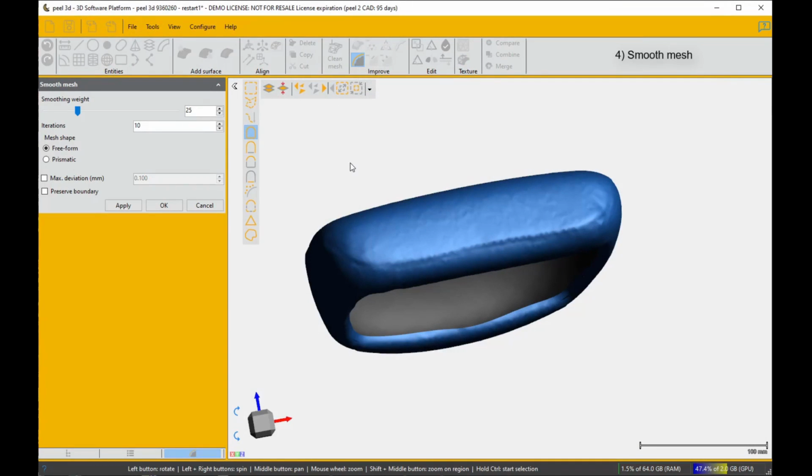Now, I'm actually going to stop the video for just a second and talk about symmetry. This is an object that's symmetrical, and as a pattern maker, you want symmetrical patterns, even if the object, which I just scanned, is not truly symmetrical. Now, our scanner is good enough to pick up the differences, but you don't actually want those differences. So from this process forward, I'm going to do a symmetrical scan. I'm going to cut it in half and make all the patches symmetrical. Now, if you have an asymmetrical object, you do not need to do this.